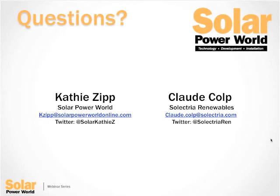For the Arcom, is there a version that uses power locally via a DC-DC converter connected directly from the PV source so that you don't need the extra control conductors? Currently there is not. However, it is something that we are currently evaluating. What happens is the power requirements are very, very low, and at 1,000 volt DC to 24 volt DC, the circuitry and the components in order to do that are not very mainstream, so everything's very, very expensive and rare to find. So we're evaluating trying to make that install even easier by looking at DC to DC conversion, but at this point in time, there's no option available.